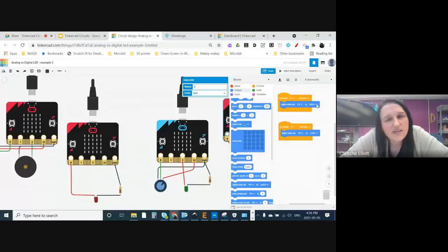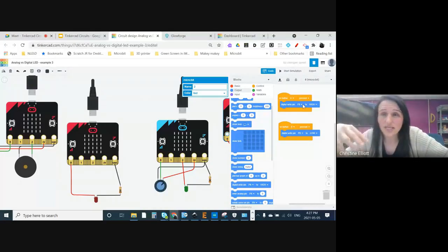Yeah, like I think if I'm not mistaken, in MakeCode, this one here, digital write pin, you'll either set it to 0 or 1. 0 meaning low, 1 meaning high. In this case, they're giving you two options. They're saying low or high. But in MakeCode, it would be either 0 or 1. You're only given two options. So there are some slight differences here, but nothing too major.